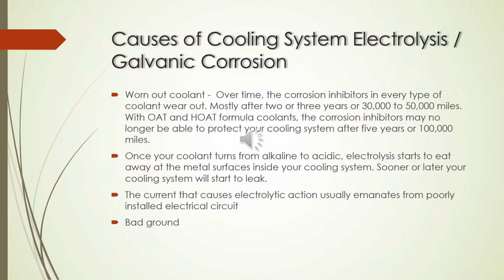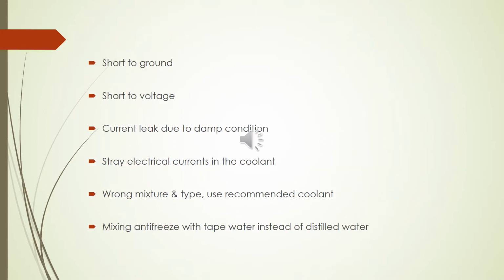The current that causes electrolytic action usually emanates from a poorly installed electrical circuit. That current, we call it stray current, and there are various reasons that I'm going to outline that cause that stray current. One of the reasons is bad ground.